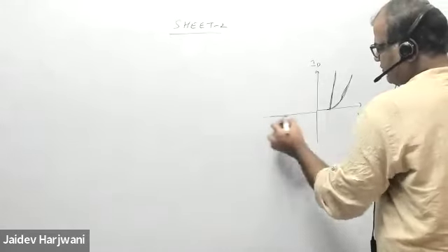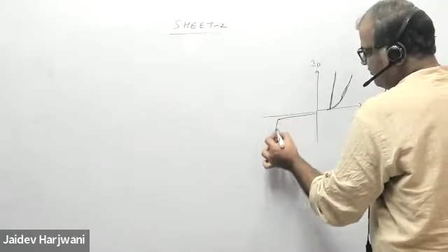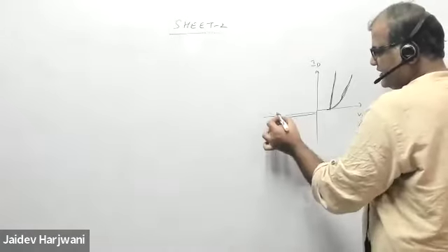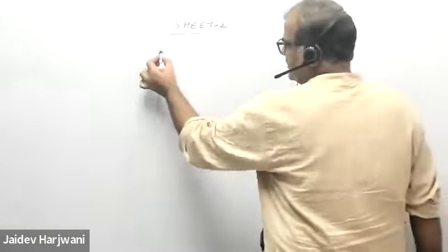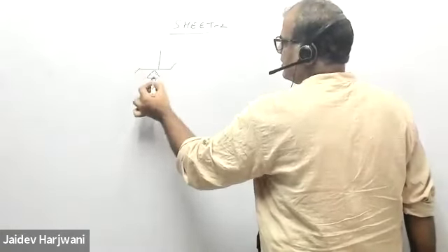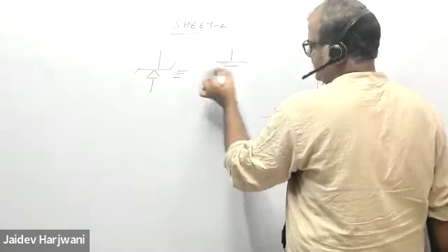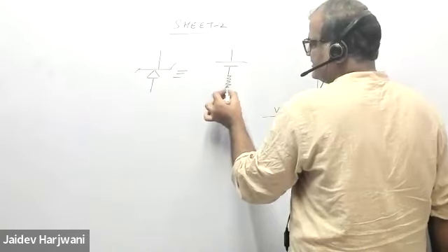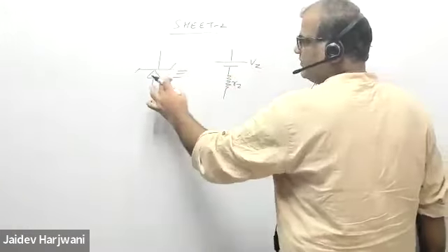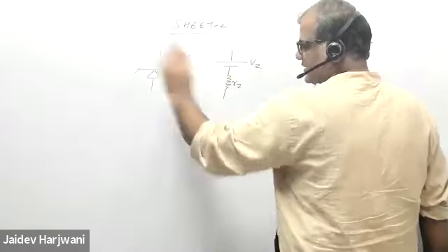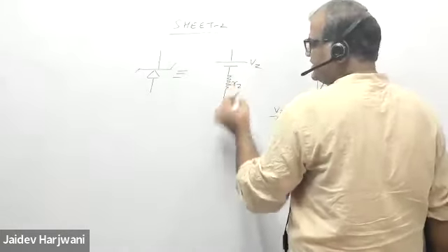Similarly, if I want to plot the IV characteristics in reverse bias, then generally we plot it like this, straight. So the Zener voltage is fixed. But if I replace a Zener diode with a battery in reverse bias and a resistance RZ, say RZ and VZ. Generally, we replace a Zener diode in reverse bias, if the voltage is greater than VZ, by a battery. But here we can also replace it with a resistance.